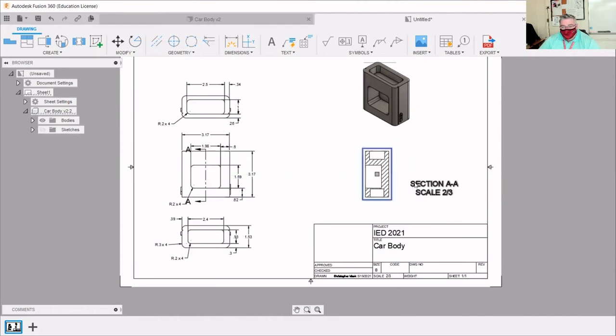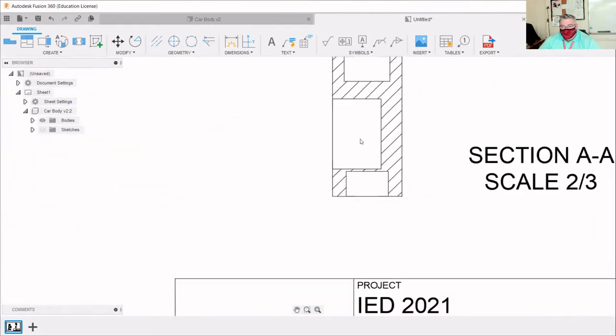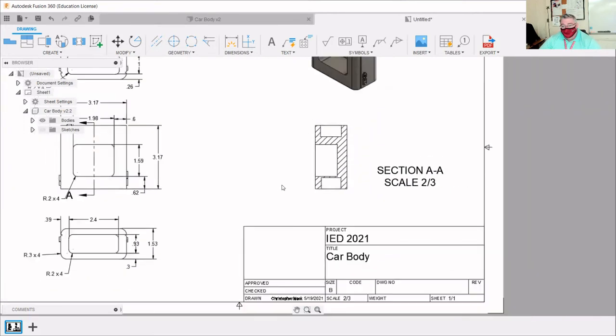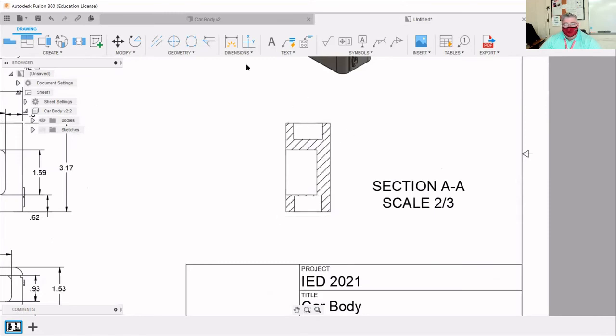But it's this view that now allows you to see the depth of the 3 holes. And those diagonal lines, those are called section lines, and they indicate solid material. So all the diagonal lines are all the wood. And then the areas that don't have diagonal lines, those are your cutouts. So here's where we're going to dimension the depth. And all you need to do is dimension depth. You don't need to dimension anything else.